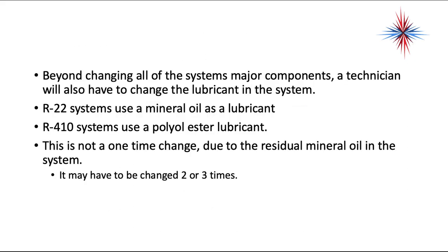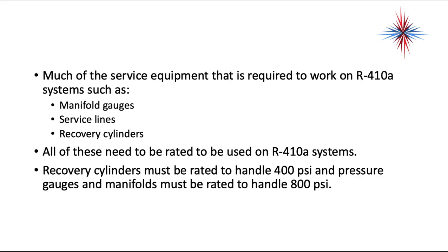Beyond changing all of the system's major components, the lubricant has to be changed. R-22 systems use mineral oil. R-410A uses polyester oil. They do not match. This is not a one-time change due to the residual mineral oil in a system. It may have to be changed 2 to 3 times.